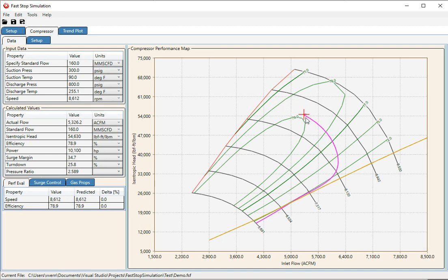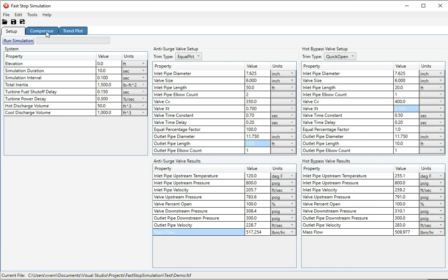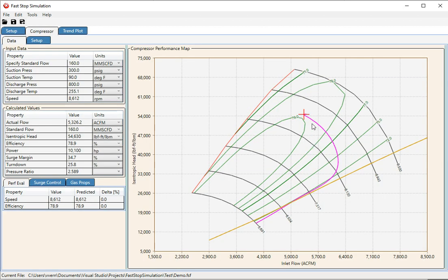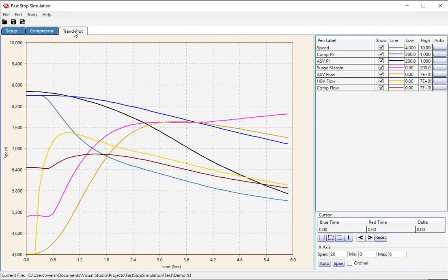So the valve opened fast enough to avoid much of a decay in surge margin. That small, quick opening valve immediately started moving gas from discharge to suction. With that small volume, that 50 cubic foot volume on the discharge of the machine in the hot section, it was having no trouble at all dropping head faster than flow would have been going down. So with head dropping off so quickly, flow actually goes up. So the machine is decelerating and depowering, but with the head dropping so quickly, it actually flows in an increasing trend.